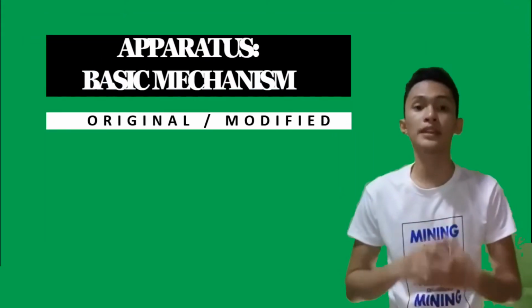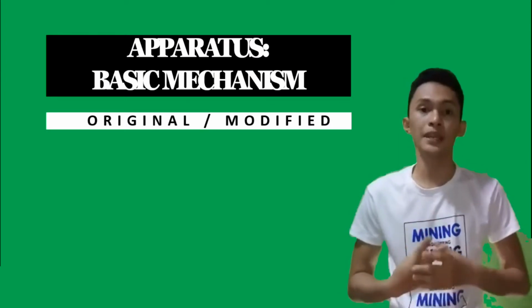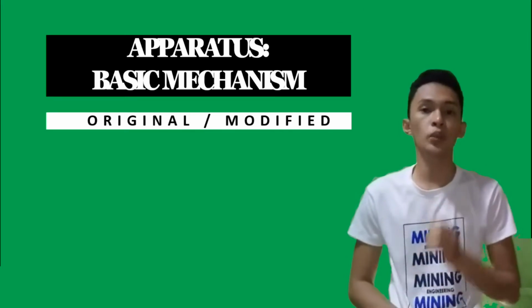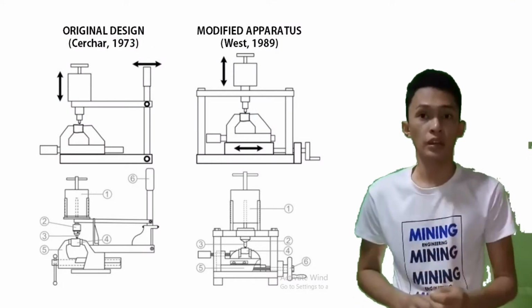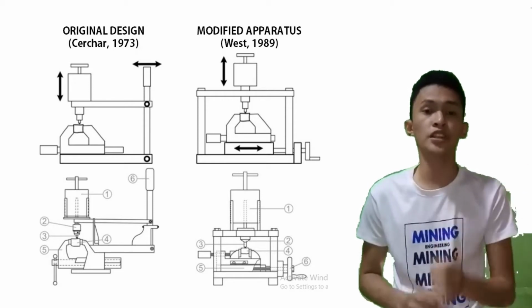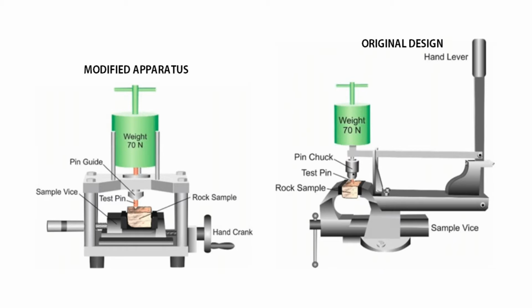Now, let's go to the basic mechanism. There are two fundamentally different mechanisms to actuate the relative movement between the stylus and the rock surface. In the original CERCHAR design, both the stylus and the dead weight are made to move across the stationary rock surface. In the case of the West design, the rock samples move under a stationary stylus.